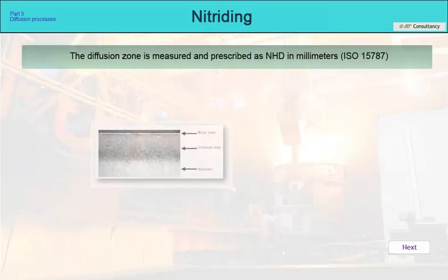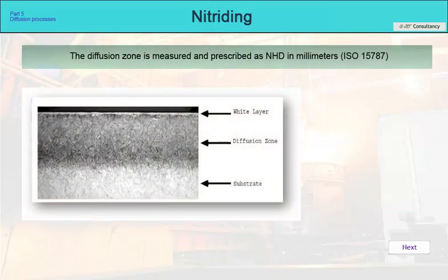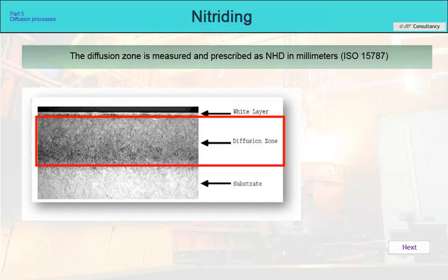The nitriding layer usually has several zones. The diffusion layer is a solid solution of nitrogen in alpha iron. No phase transformations occur in this area, only the internal compressive stress in the layer increases due to the lattice gain due to interstitial nitrogen.